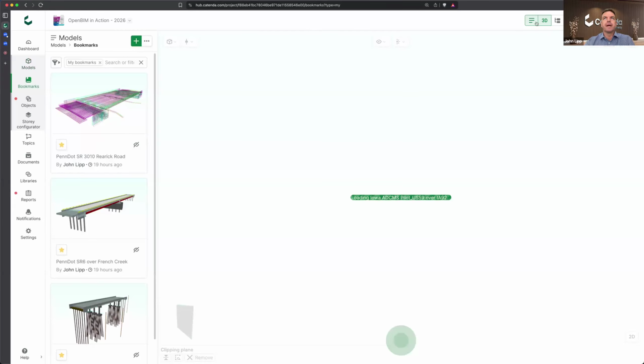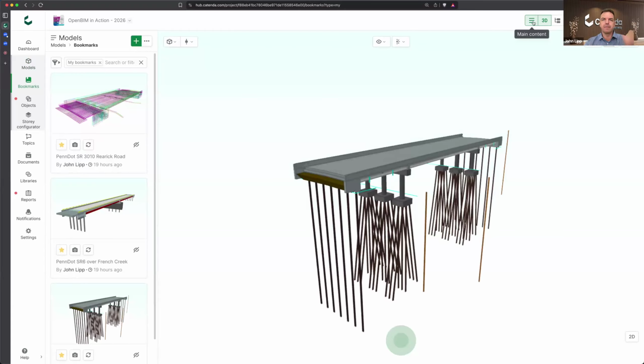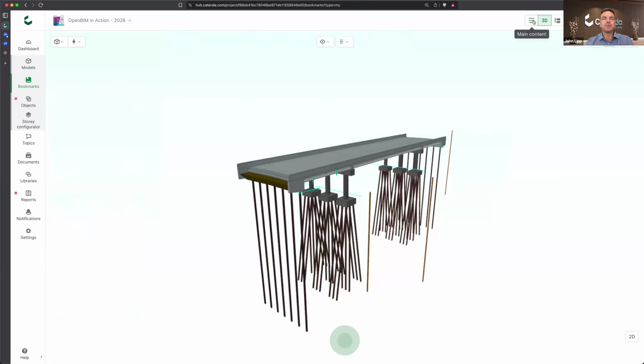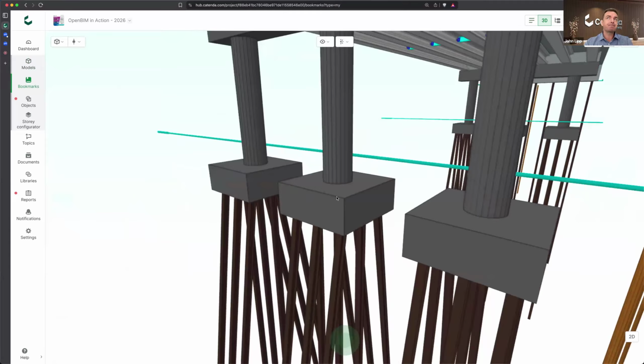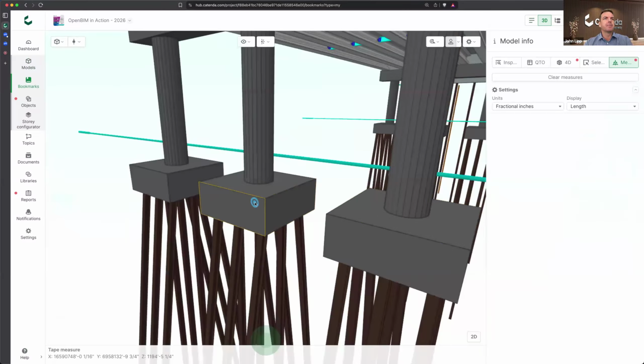It'll just then take me to that location. Again, normally your project will have multiple projects in different locations, so it's just now isolated those models and changed the camera position using that bookmark. And from here, I'll turn on my measure tools. And just like a tape measure, you basically pick one spot and drag and click it to another spot.